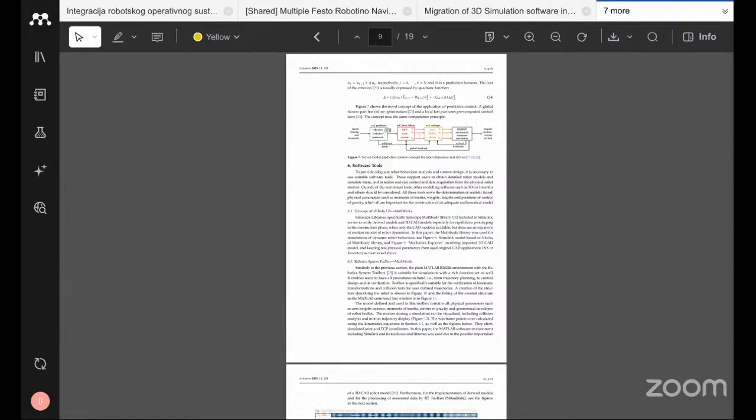During the initial stage of robot development, a 3D CAD model will be available, but dynamic equations are not available, and there is no physical prototype. In this case, we can use the Simscape Multibody CAD model. We can convert this into an executable physical model. So before manufacturing the prototype, we can simulate the robot. This is called rapid prototyping.